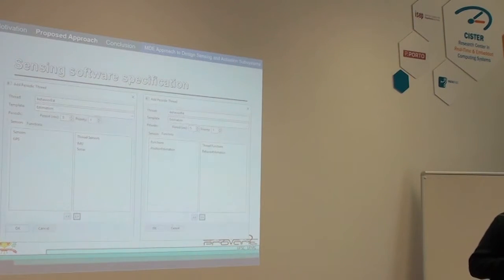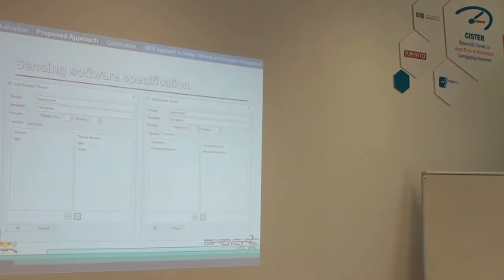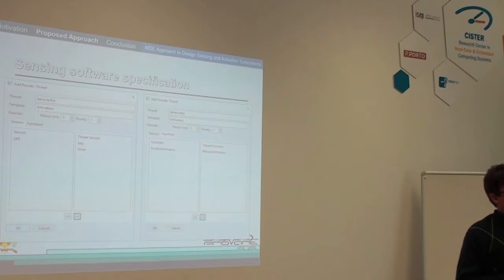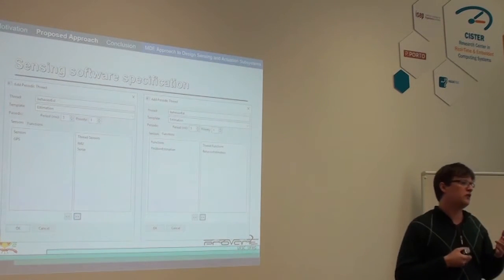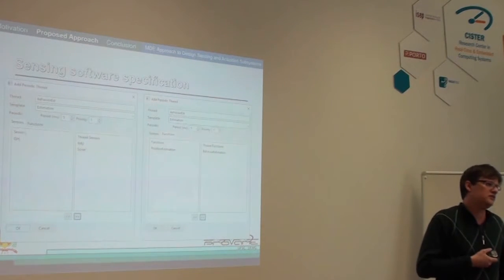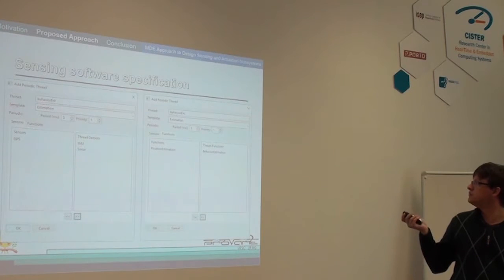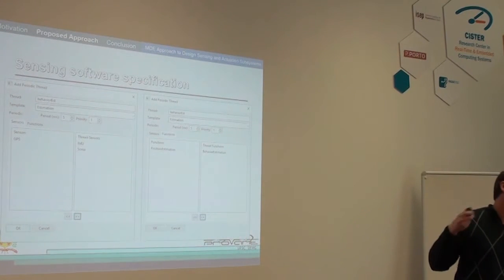What does priority mean in this case? AADL also works with a specific property that is priority. I think when you perform the schedulability analysis directly on the model, it uses these priorities according to the specific model of schedulability that we use to perform the analysis. So we need to specify the system priorities on the threads of the AADL.